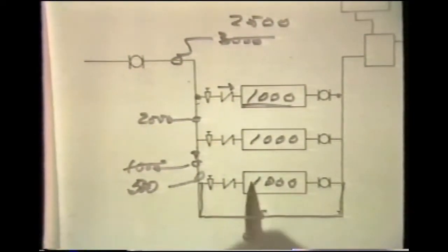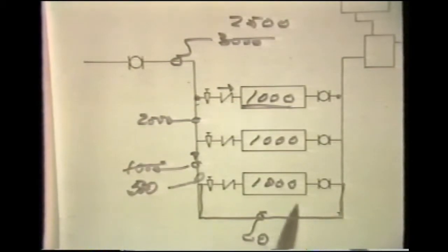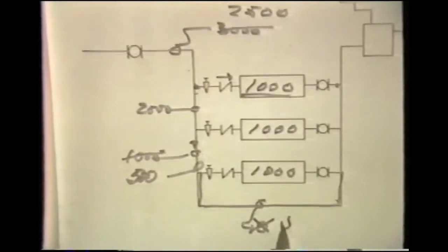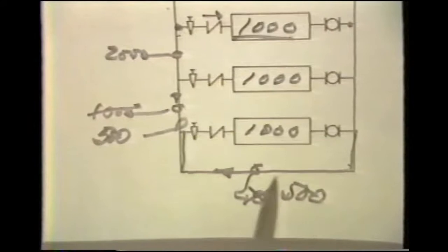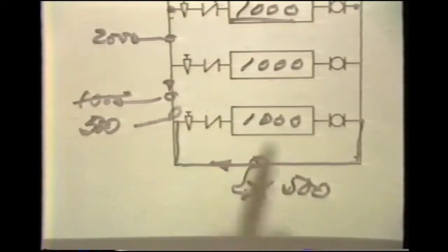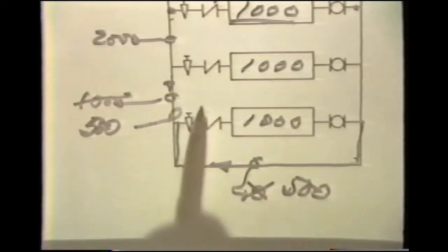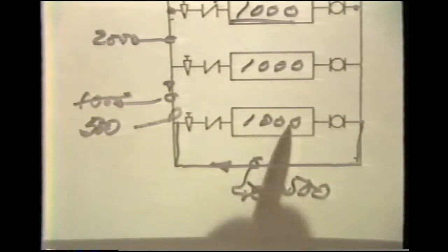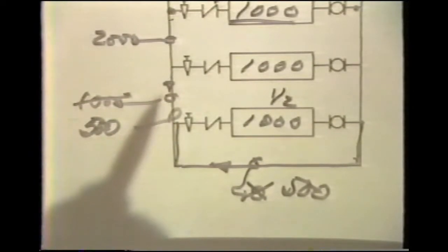Now, if that chiller pumps 1,000 GPM, and indeed it must because of the considerations of piping pressure drop in this illustration, what would happen would be that we would have 500 GPM in bypass, the 500 GPM of leaving chilled water mixing with 500 GPM of return water from the system. So the chiller would then operate at 1,000 GPM, but at 1/2 load.